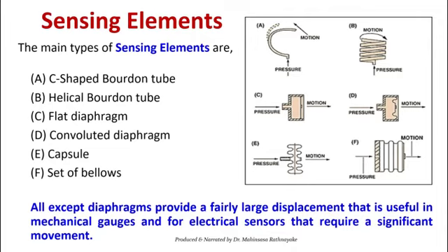This creates some problems with diaphragms, because since the displacement is very small, how do we relate it to pressure? It has some effect on measurement accuracy or sensitivity. Of course, I will discuss that part when we come to the diaphragm. Actually, this barrier has been overcome by technology, and now, out of all these sensing elements, the most popular ones are the diaphragm and Bourdon tube, right?